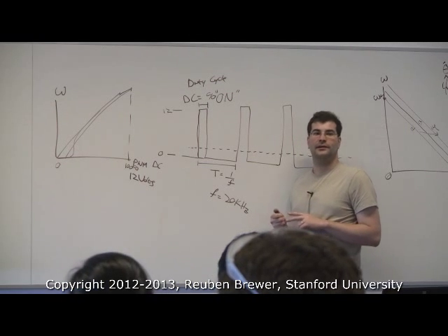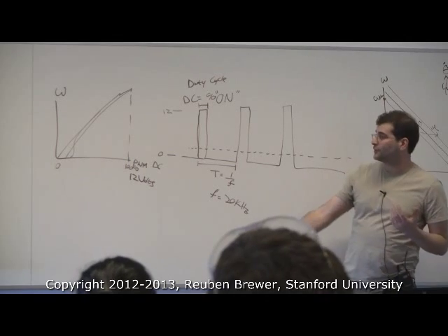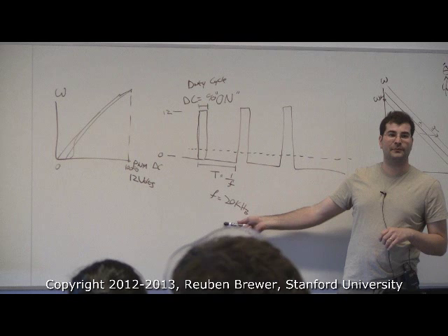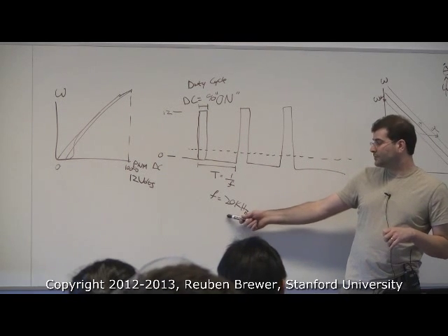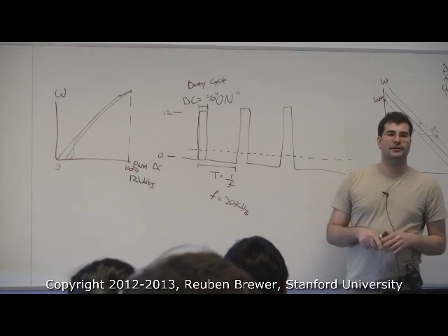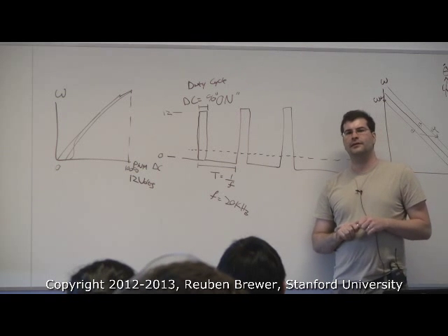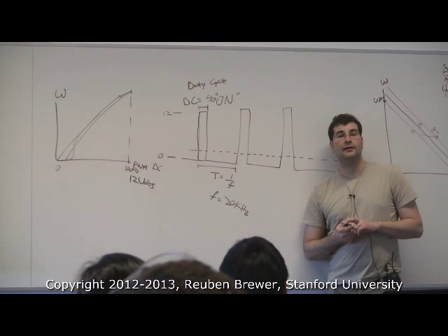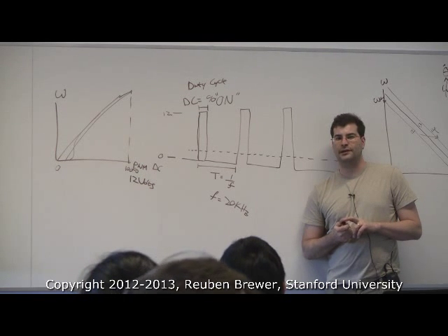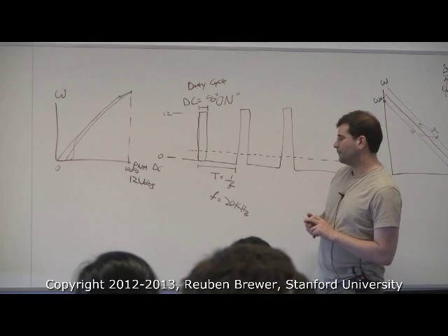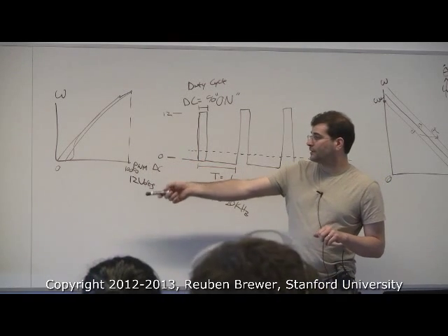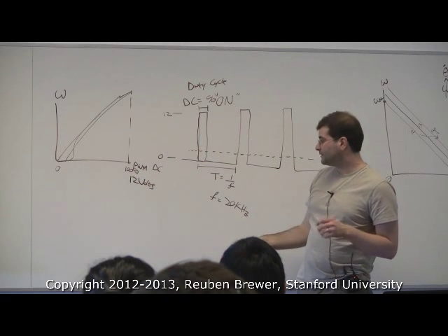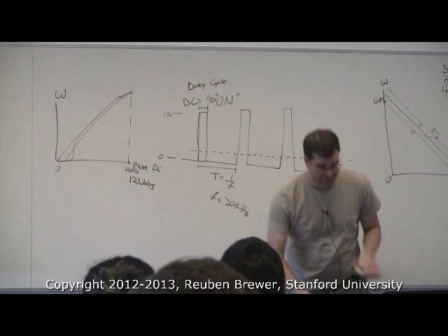A little higher. You want to go, I mean, there's no reason not to. You're getting better linearity. And there's another benefit I'm not going to go into here, but basically bumping up this frequency, within reason. I think, Rob, what did the Copleys use? Not sure. I think it's above 40 kilohertz for the Copley amps. Basically, you get better linearity between the PWM and the actual speed of the motor. So it's a better speed source, and you don't hear it. It's less annoying.